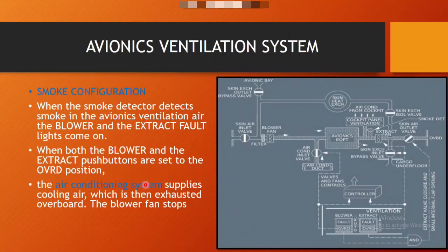So here if you see another example, I have talked about partially open. Suppose you are applying MEL procedure, deactivating outlet valve in closed configuration, then you have to open the small flap through whatever AMM is suggesting. This is because I am just sharing for knowledge.